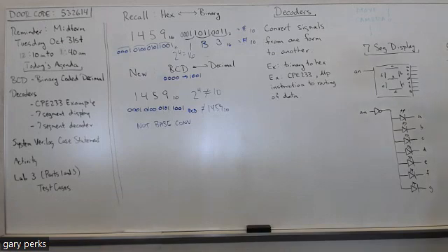But if you take a look at this control unit decoder and you look on the left side where the inputs are, in the upper left of that control unit decoder, you'll see IR[30], and then IR[14:12], and then a little further up, there's a 7-bit input.